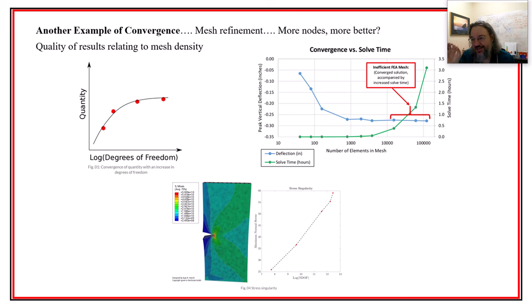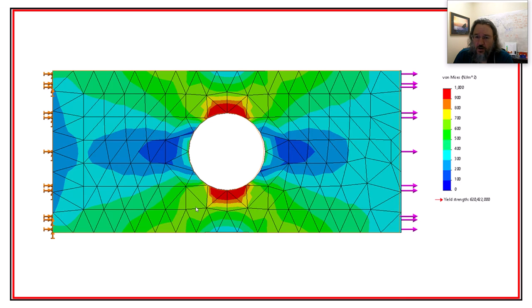But if you refine it in the place where there's a really hard notch, you might find that it just keeps going up. So you can't believe the stress that you got in the earlier, less refined mesh, because you have a singularity. This is just one example where that might come up. So in order to interpret the results, you really have to be aware of this happening.